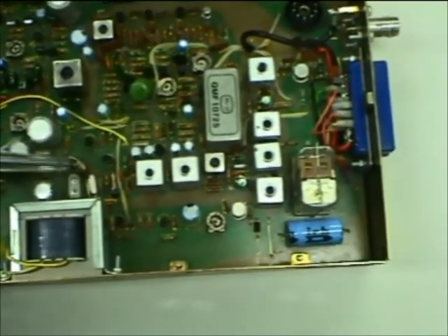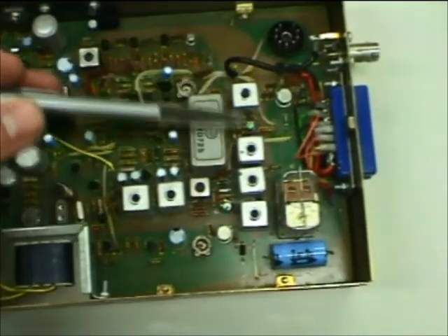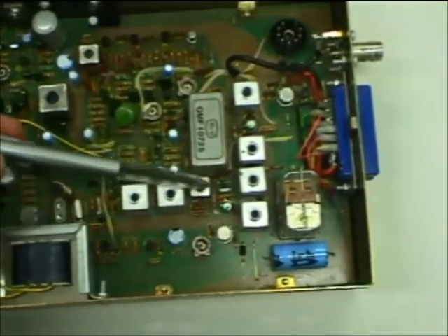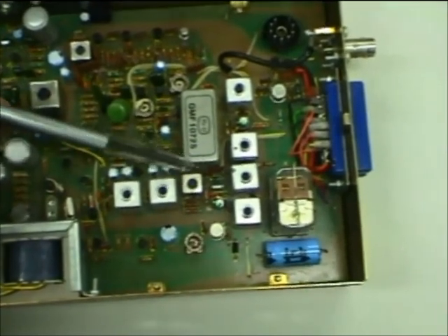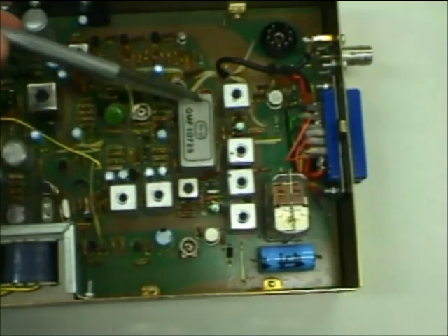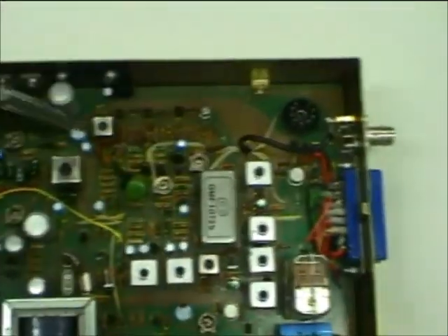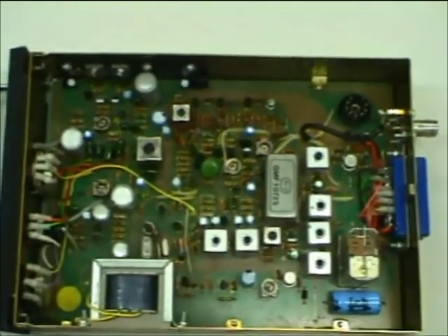So that's feeding frequency 2, if you like, into the mixer, and frequency 1's coming down through here, and then the sum and difference hit the filter, but only one of them will be the one we want. So 10.7 will be the difference probably, and the sum will be something much higher, so it won't get through that, and then on it goes through the rest of the receiver.